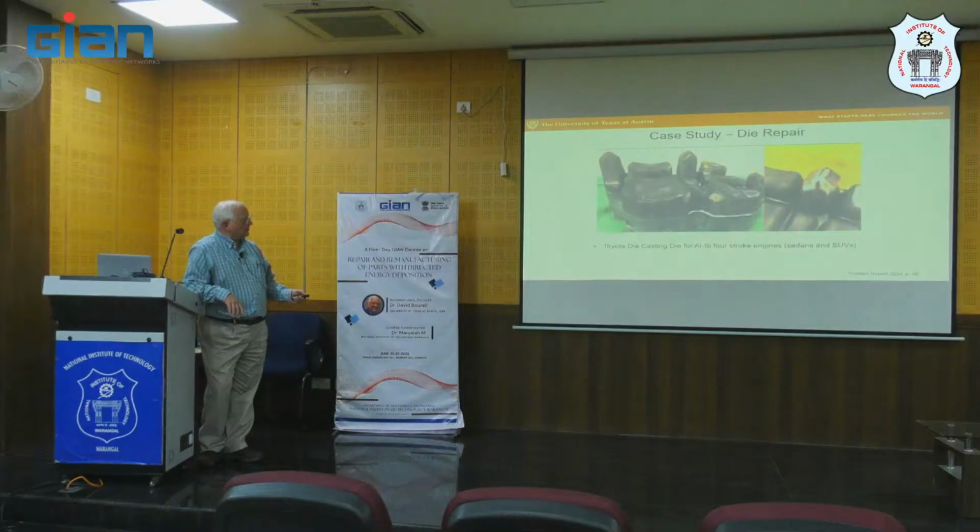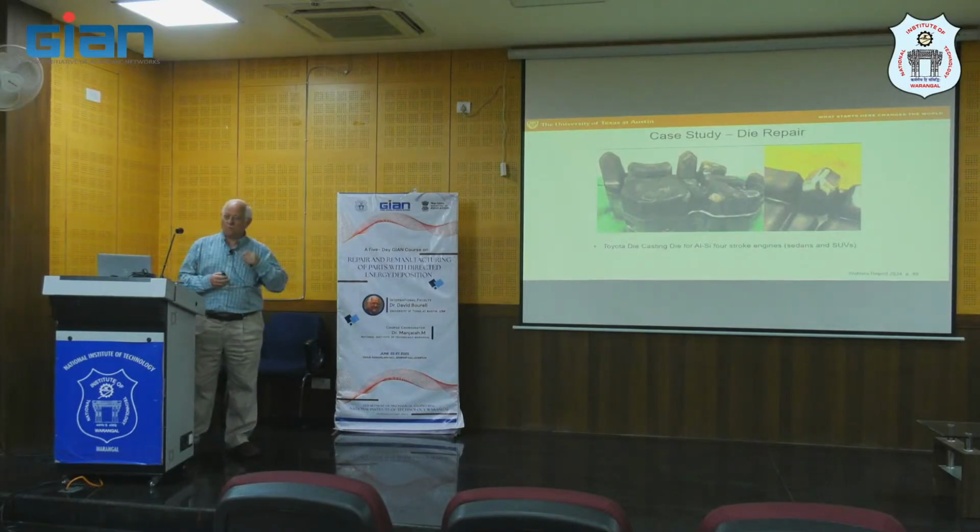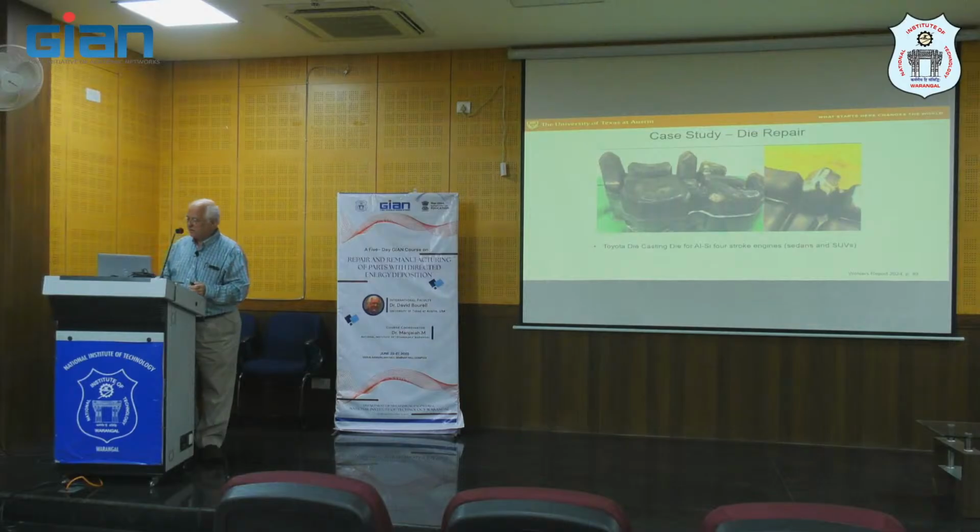And you can see here that they're sort of putting a cap on a tooth. They come back in and have added material and then machined it out to refurbish the die set. So this is the common theme for repair in directed energy deposition.